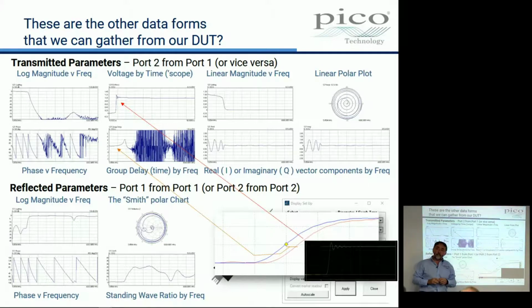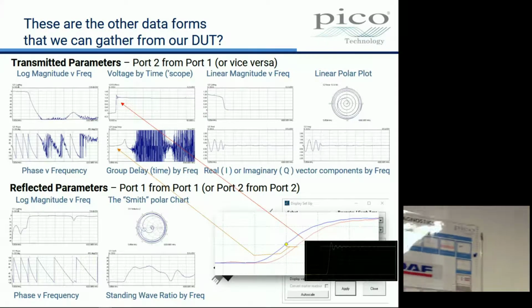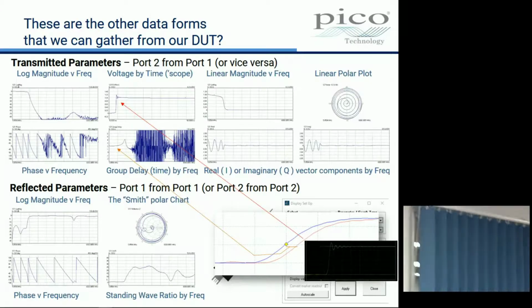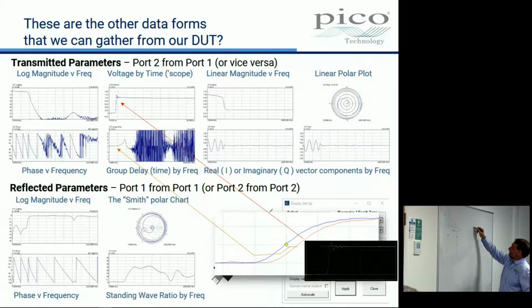Now the other thing it does, you remember I said our step has this spectrum. So what happens when you add all these bits of spectrum up, I'm sure we've all seen it in terms of a square wave. We draw the fundamental, and then we draw the third harmonic, and we draw the fifth harmonic.